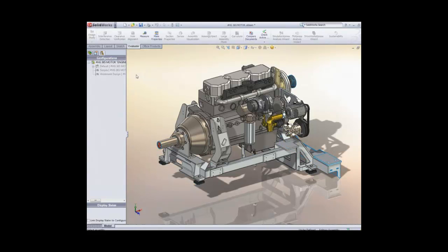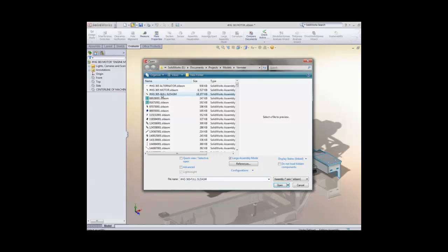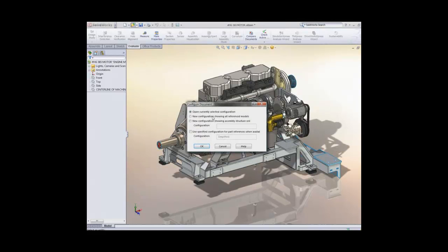Doesn't look any different? Well, it does when you move the mouse over the assembly. The faces that don't really exist are removed, so we can clearly see which faces have been included and can be referenced in the top level assembly. Notice also that the assembly file has no parts, making it extremely compact, easy to email and impossible to reverse engineer. Now let's open the main assembly, this time using the advanced option.